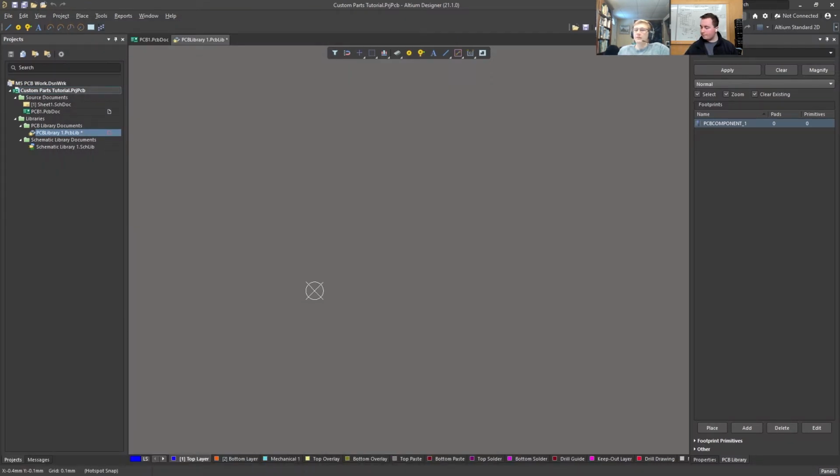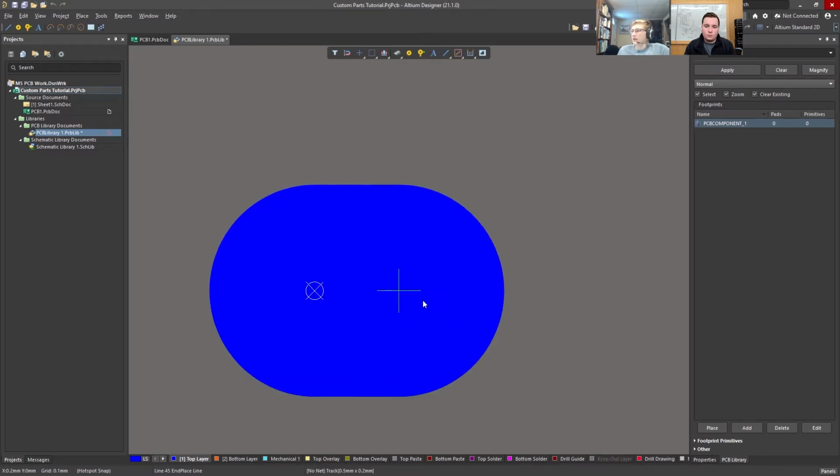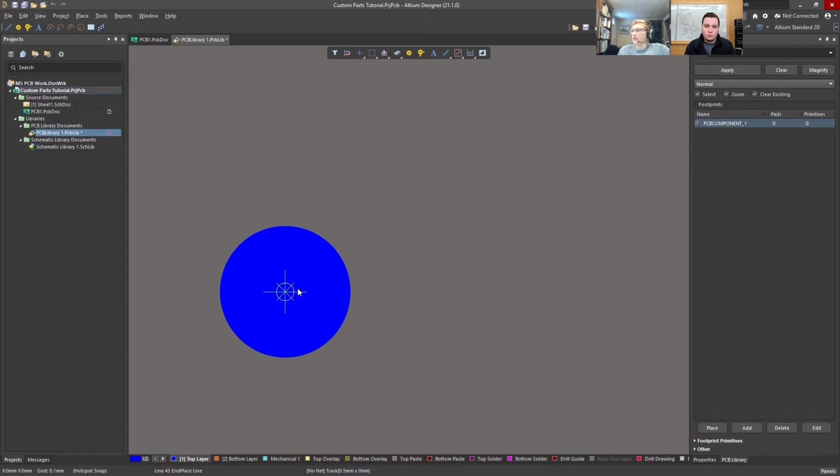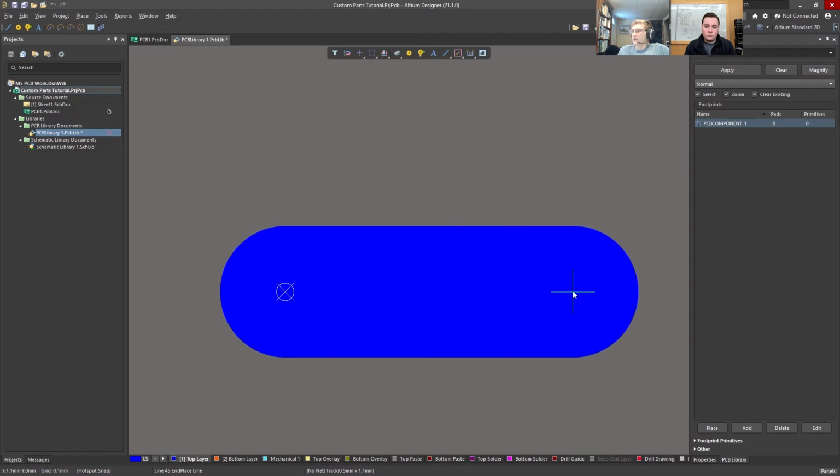So here's the thing. What would be nice is if when we put the chip on, the silk screen, the definition of the edge of the board, was completely covered, so that you didn't see some of these notes that we're making now to help ourselves. And it would also tell you that your chip is aligned. So we're going to draw a square in a second, and what we'd like is for that square to be completely covered. That means we're not just going to start a line here. This is on the wrong layer, but you get the point. And then go 3.5 millimeters, because it would actually extend beyond 3.5 millimeters, right?